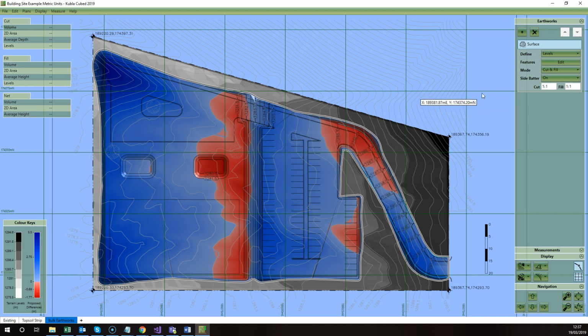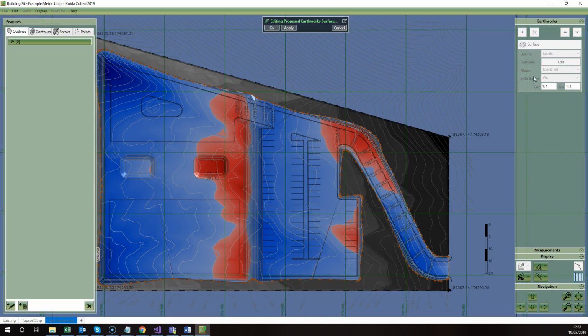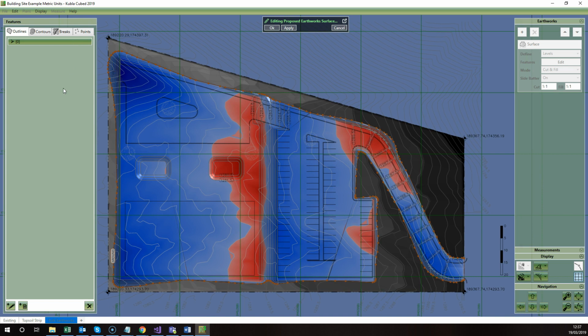So now if you click on edit surface, you'll notice that the editor is the same, but you now have the rest of the project assets still visible, so you can align and even snap boundaries to other site assets. That's useful in the feature surface for moving, say, the boundary of a feature surface in context to a building pad that you might have created using a platform.